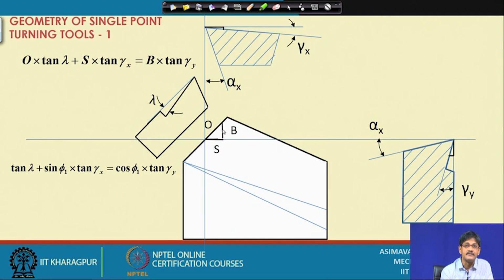Whole trick is that you correctly assume the triangle here. This triangle means that you are establishing a relationship between three vertical distances. The vertical distance you travel down along the cutting edge in this case, that means this way you are traveling down the rake surface on the cutting plane.